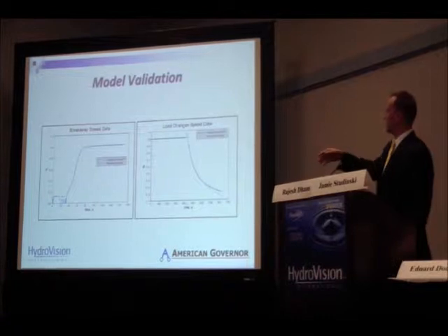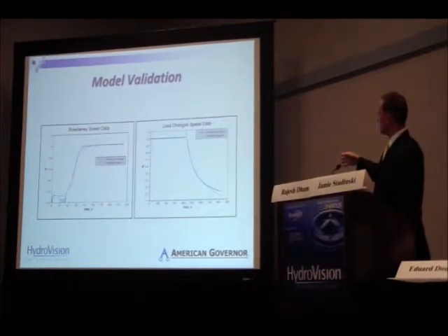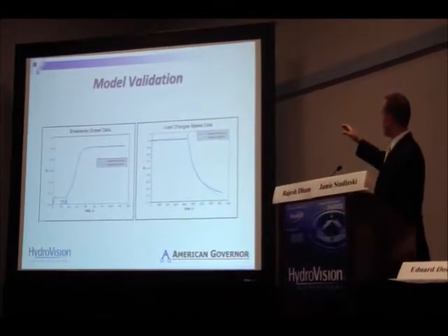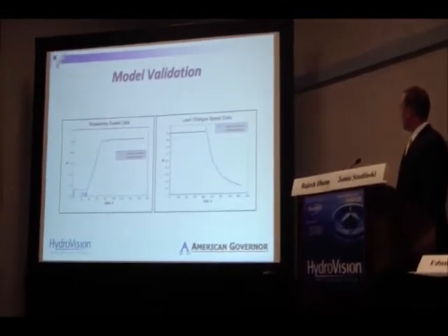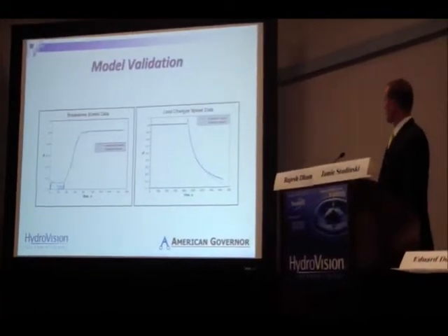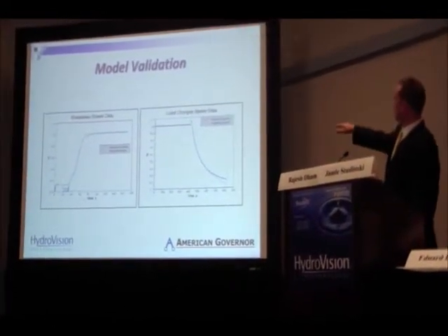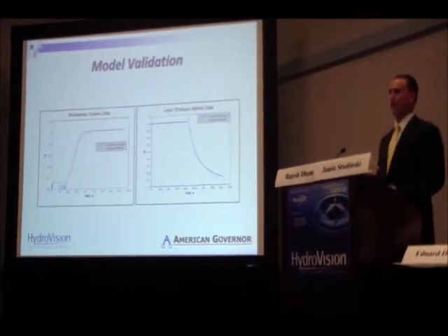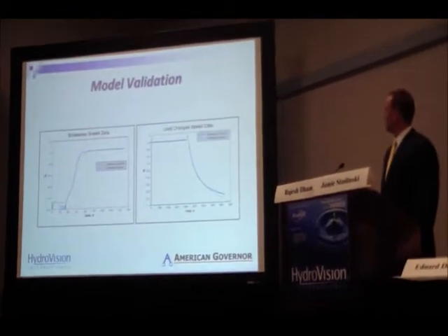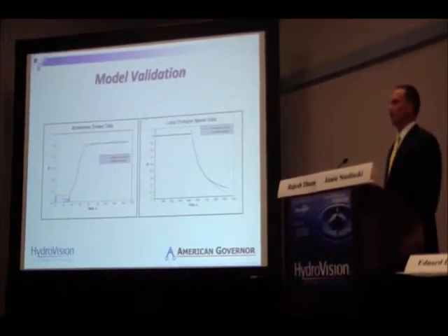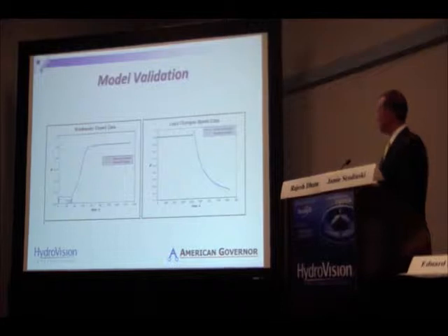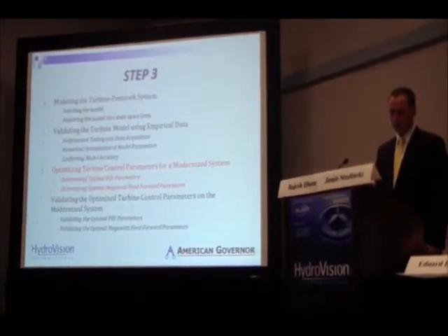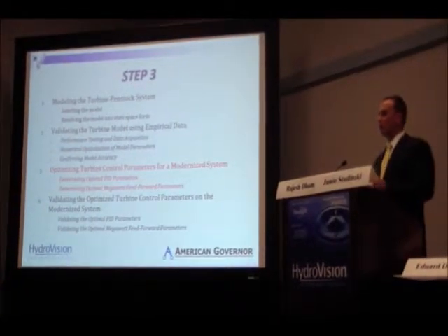So we can see here, we have a breakaway routine, we have a load rejection routine, and we can see that our speed, it's almost hard to see in certain sections, but we have a measured and modeled speed, and we can see that they're in good agreement for most parts. When we get down near the lower end, we have some issues with the way that they ran their high pressure lift pumps and how that affected our model as compared to reality. But for dynamic, online testing, anything where you'd be up to standard speed, we can see very good conformance with the real plant data.